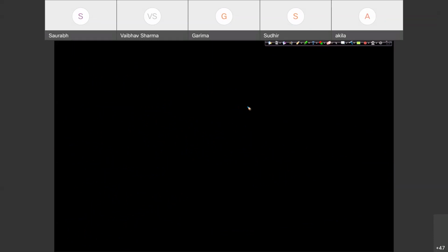Just give me a second, please. Sometimes it takes a little time. Okay, so this is my sensor. We are not talking specifically about a sound sensor. This is a sensor which gets analog environmental data, converts it into digital, and we are trying to interface it with the digital pins of Raspberry Pi. We have connected the sensor with the Raspberry Pi. Here the sensor is connected with pin number 7, or GPIO number 4. There were 2 more pins of the sensor.